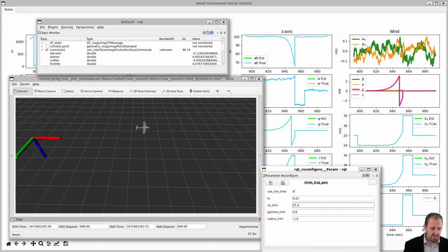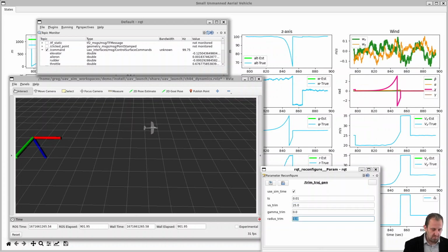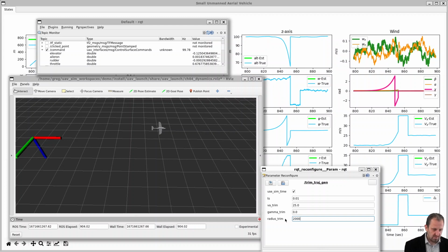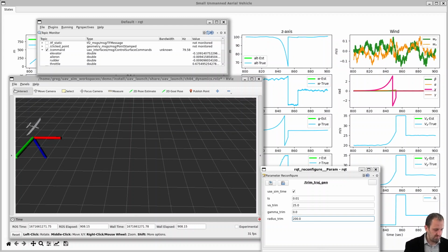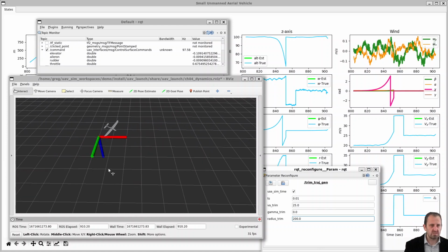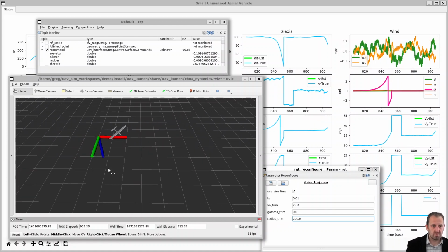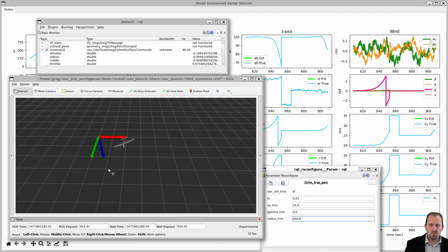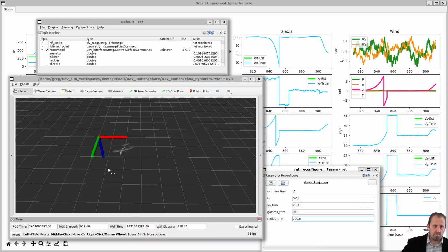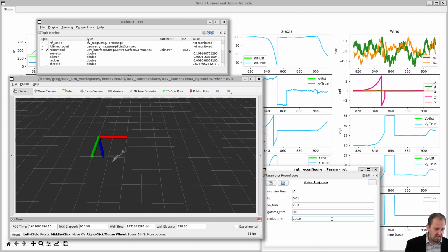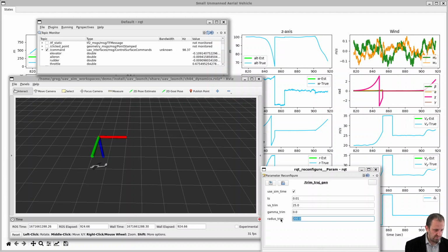Another thing we do is this coordinated turn, which is the very first thing we'll actually do. If we want to turn our aircraft, instead of doing a skid to turn using our rudder, we'll use a bank to turn. So you see that there's a large bank, a large value of phi.